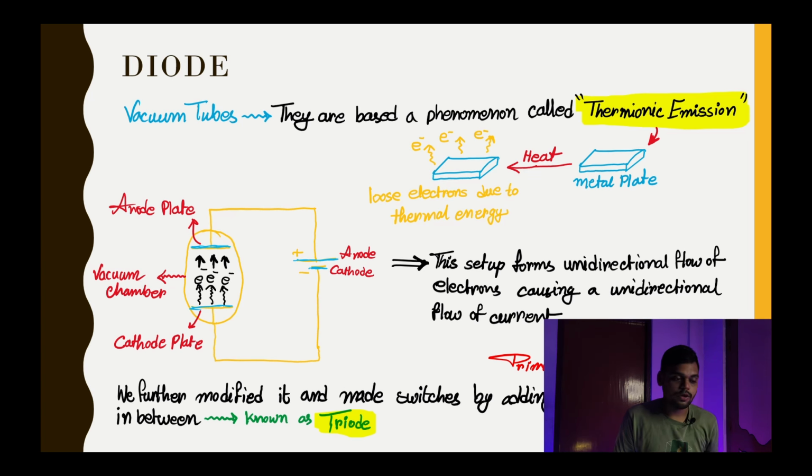Once the electron flow is happening, we can say the positive charge flows opposite to the electrons, and hence current flows in the circuit, and it is strictly in one direction. The cathode radiates electrons and those electrons are free, but due to the electric field lines from the anode to the cathode, the electron will feel a force opposite to the electric field lines.